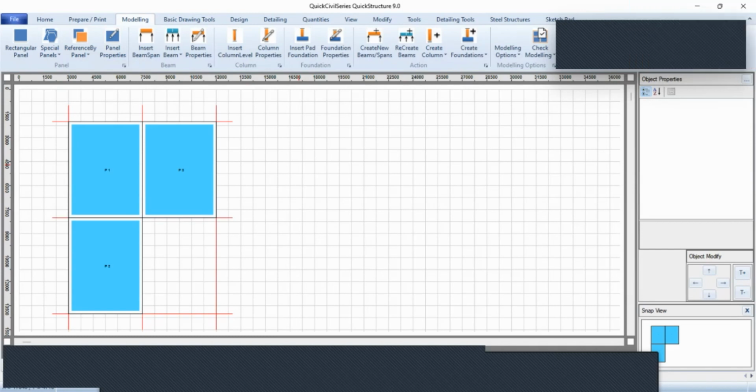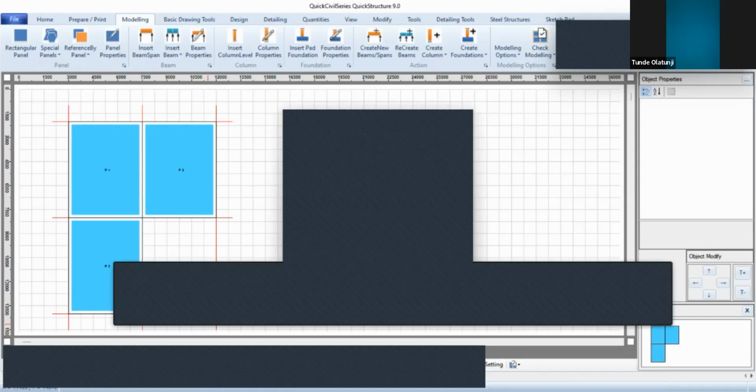Most of the times we mix the two up, and then if you come to site, if you see where a cantilever beam is carrying a slab, most of the times you see people still reinforcing the slab as if it is a slab that is cantilevered. So we are going to use this also to show the difference between the two, and also see how we can navigate through our problems using this method.